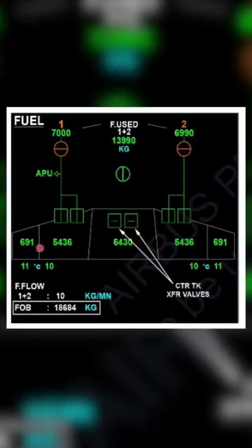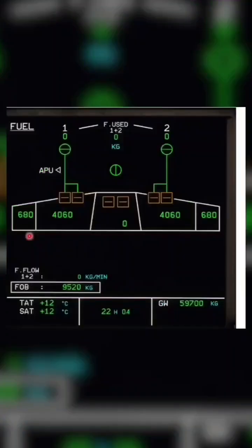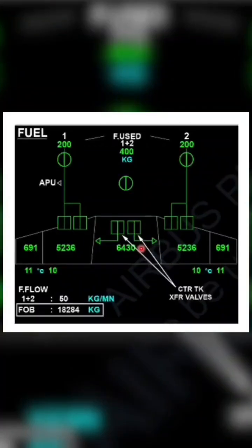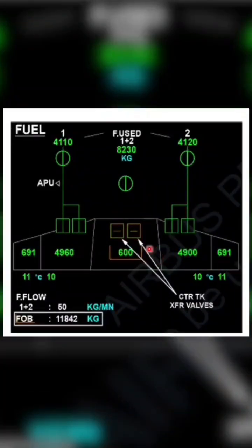So this is your fuel quantity indication. We'll discuss this fuel quantity. It will normally be green color, on any page you open it, and the unit may be either kg or pound depending on the DMC pin programming. So we are using kilogram here. Two dashes appear across the last two digits when the fuel quantity indicator is inaccurate; only then will these two dashes come out.